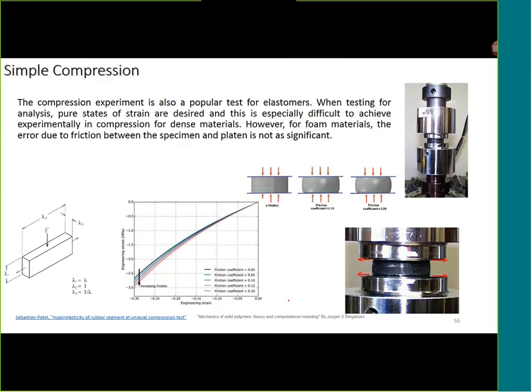The simple compression is important. One of the important challenges while conducting the simple compression is that we need to induce a pure compressive stress state. It means that when you compress it, this material should not stick with friction.